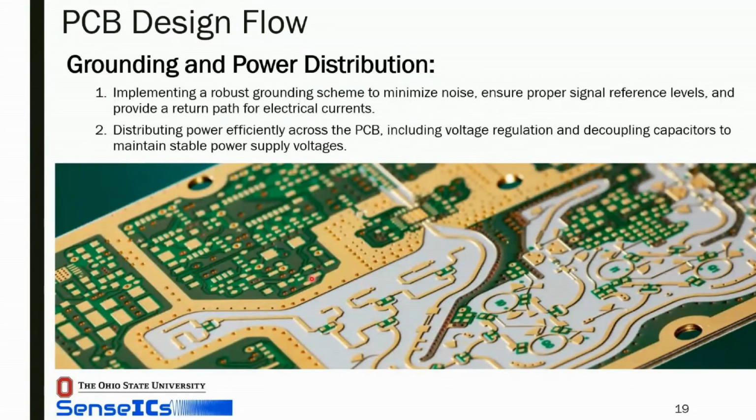Not Josh or Dominic. Go for it. So these vias are stitched in a circle around this thing, which makes me think that they're probably trying to shield either what's inside of it from emissions outside of it, or what's outside of it from emissions inside of it. Exactly right. Or both. Shielding something from something else across that boundary. Exactly. That may not be the complete answer, but for the sake of what we're talking about,